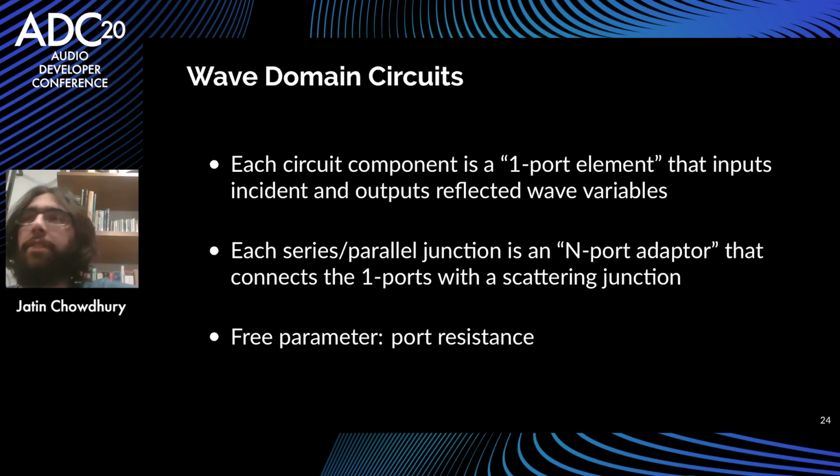But the advantage of going through all these steps is that you end up with this free parameter, which is the port resistance. So each of these series and parallel adapters will have one free parameter, or one free port resistance, that you get to choose. And mathematically, that's a really convenient thing to have, and it allows you to have a lot more flexibility in your modeling scheme, which I'll talk about more.